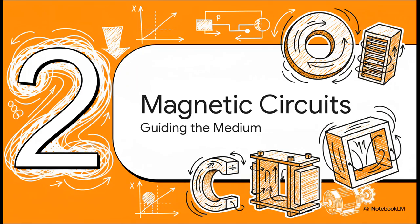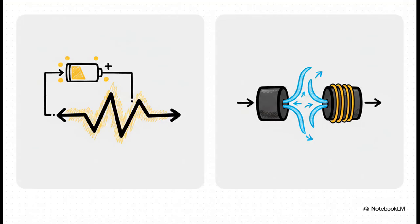Moving right along to Section 2, Mapping the Magnetic Circuit and Guiding the Invisible Medium. I absolutely love this parallel because it's a total game changer for design. Just as Ohm's law tells us that voltage pushes current through electrical resistance, well, magnetomotive force, or MMF, pushes magnetic flux through something we call magnetic reluctance. It's exactly the same logic. Instead of ripping our hair out over crazy complex 3D vector fields in free space, we can just model the machine as a simple circuit.